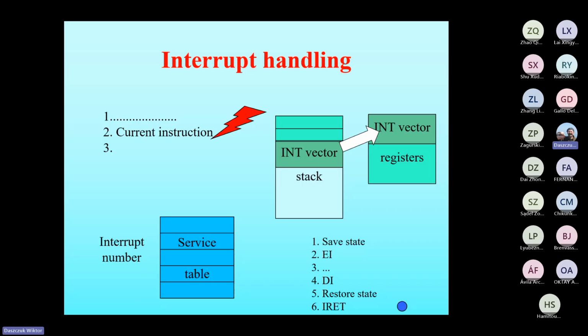the program is run in user status. Interrupts are served in system status. So we should switch between system and user state. When we accept the interrupt, the processor automatically changes to system state. IRET loads the return address from the stack and switches from system state to user state.